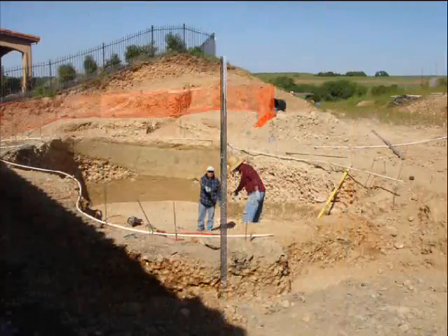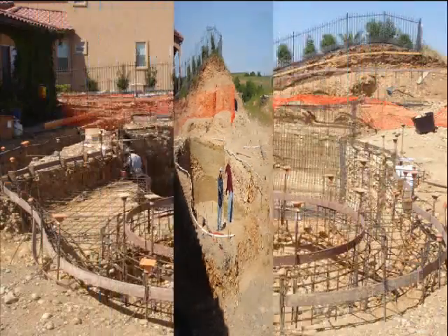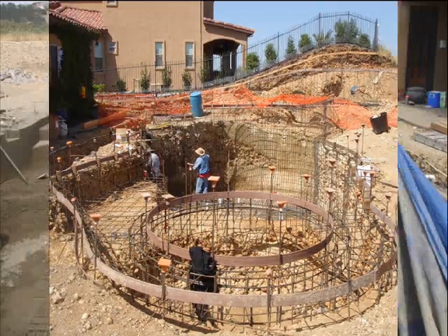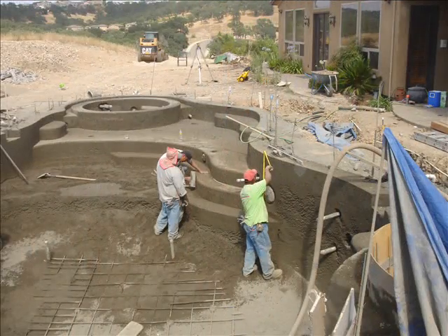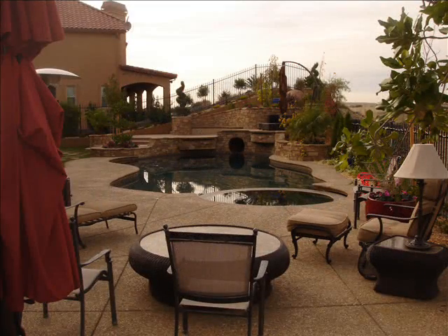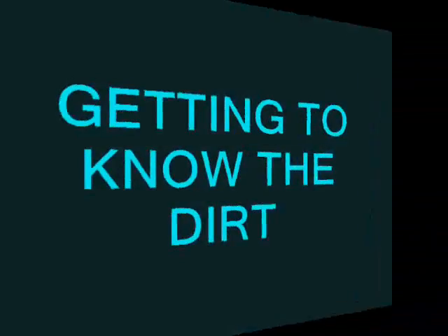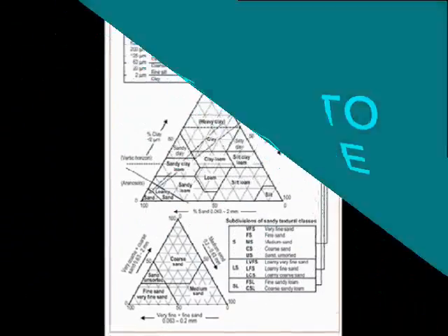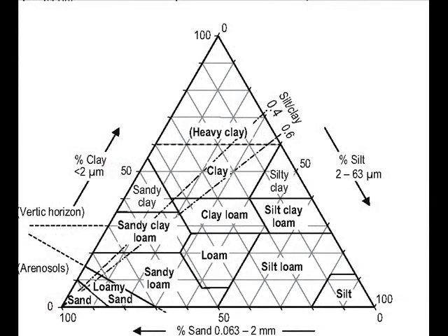In estimating the excavation volumes of a swimming pool project, several factors will weigh into the considerations. The square footage size and depth of the pool are the basis for calculations, but related contributions for calculating volume have to do with the geotechnical composition of the existing subsoil strata beneath the pool. Soils are made up of three primary components: silt, sand, and clay.